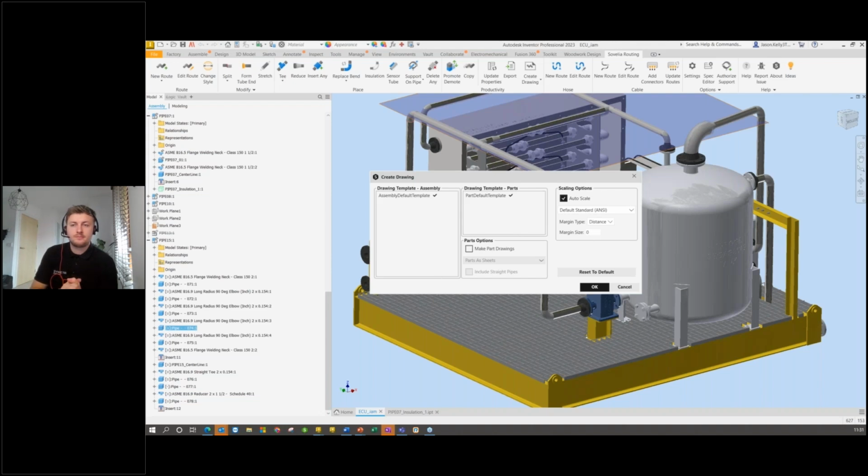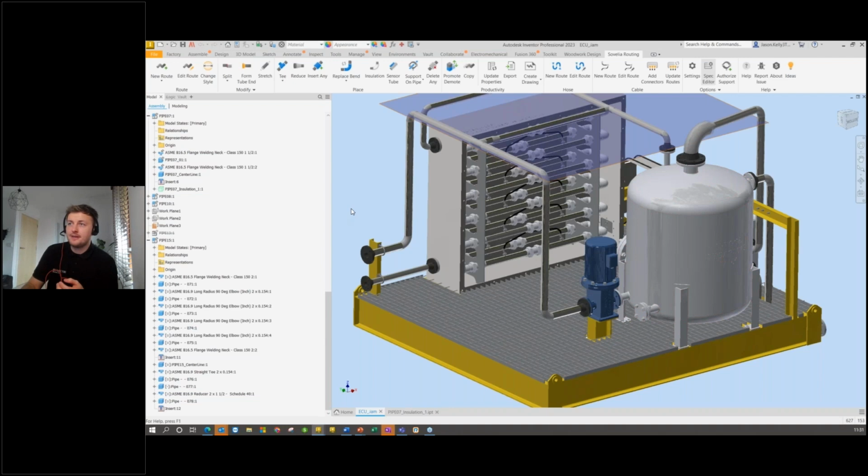Right. My other question, you kind of alluded to this when you were setting up your templates, but I'm wondering if there's an easier way. A lot of our pipe work for nuclear sites would be self-draining pipe work, like you say, it would have a fall of like 1 in 100 or something in it. Is there a way of putting that in as you model, and would it automatically cut elbows back, or would we need to set up a library of elbows that have the right angle already in them? So there is the option when you publish it to the spec editor.